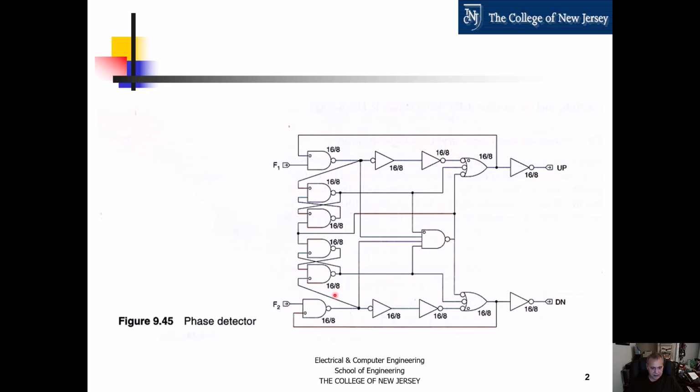But the size of the transistor, or the channel width, is going to be 8 times 150 nanometers for the N channel, and for the P channel it is going to be 16 times 150 nanometers in our case. So that explains the numbers for this specific logic-based diagram, because it changes a little bit when we're looking at transistors, okay?